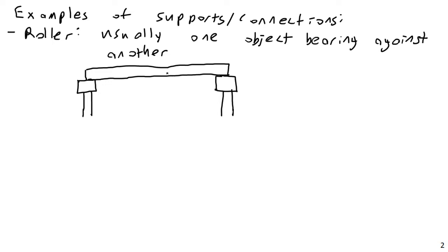If I have a crane and I pull on this beam really hard to the right, the beam is not going to cleave in two. Rather, it's going to slide off the abutment over here, or the pier over here. This really brings us to the idea of engineering models again, like you hear in many courses in statics, mechanics of materials, etc. A pin and a roller support fundamentally are engineering models. They are approximations to real-world conditions.